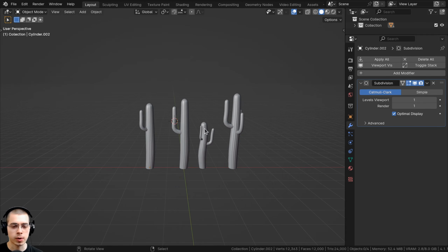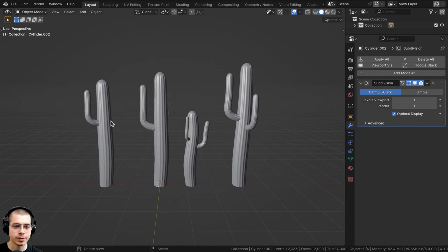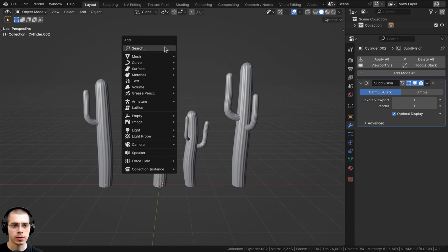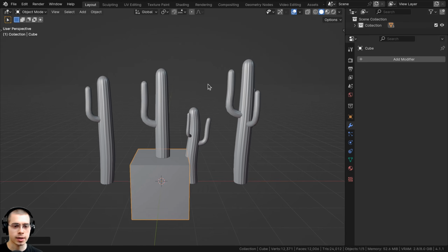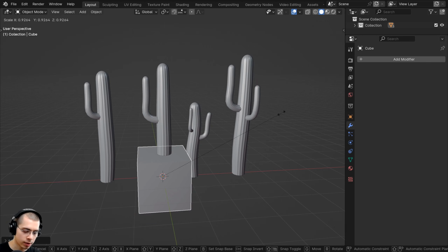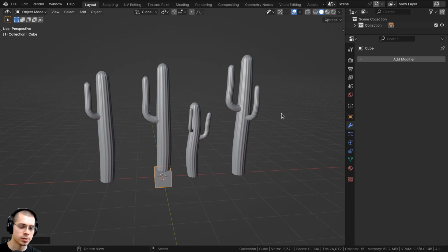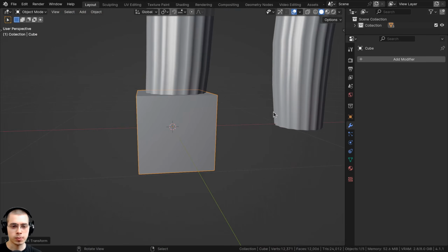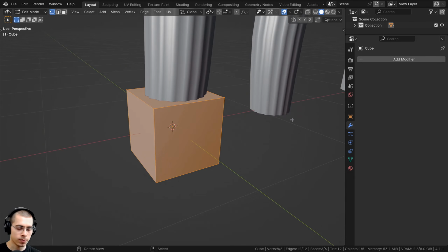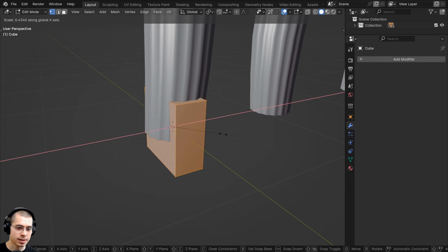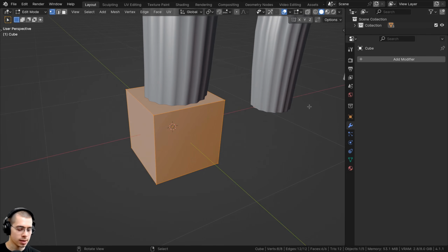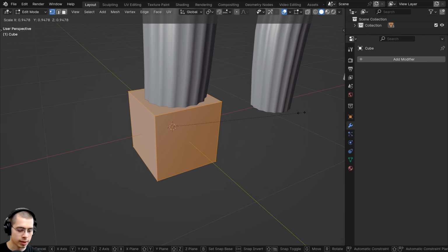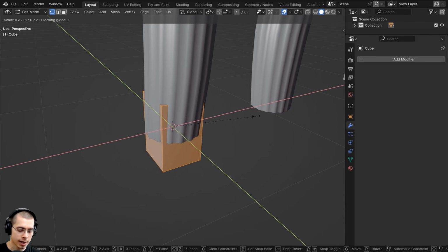So I'm now going to be creating one of the spikes. So I'll press Shift-C to center the 3D cursor, and I'll go to the add menu, and let's just add a cube. And I can scale this cube way down by like a 0.3, so it's much smaller. And then I'll press Ctrl-A and apply the scale. Let's zoom into the object, and I'll go into edit mode. And I want to scale it in on the X-axis and the Y-axis, but not the Z. So after I scale it, I'll hit Shift-Z to exclude the Z-axis, and I'll type 0.1 and then enter.